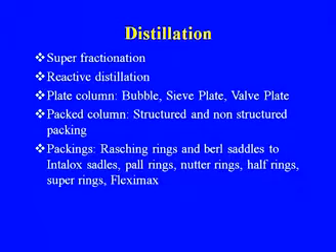So, these are some of the developments that have taken place in distillation: superfractionation, reactive distillation, plate columns such as bubble cap, sieve plate, valve plate. Then the packed column, where a lot of development has taken place, with structured and non-structured packing. Earlier we normally used Raschig rings and Berl saddles, now it is interlock saddles, Pall rings, Nutter rings, etc.